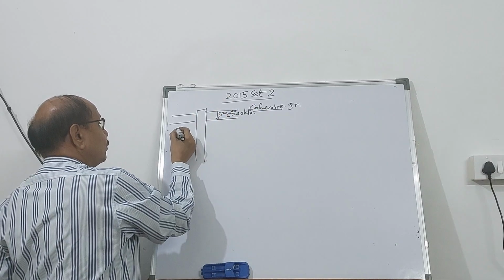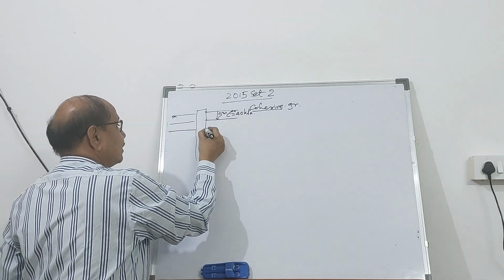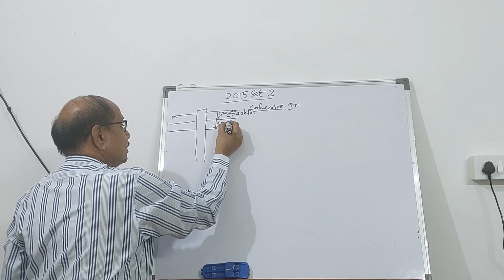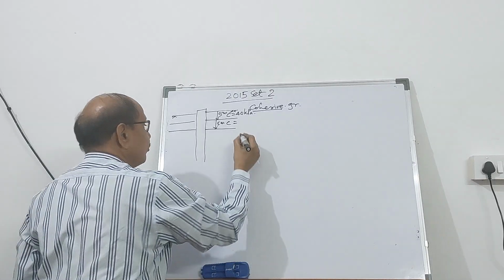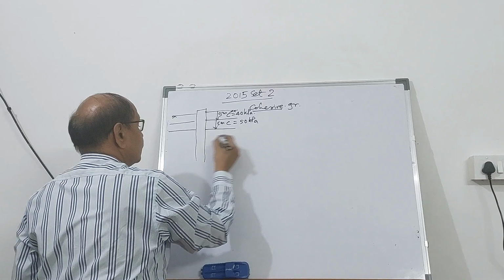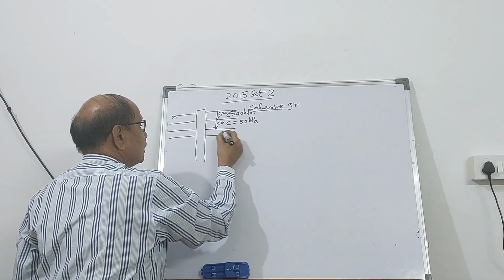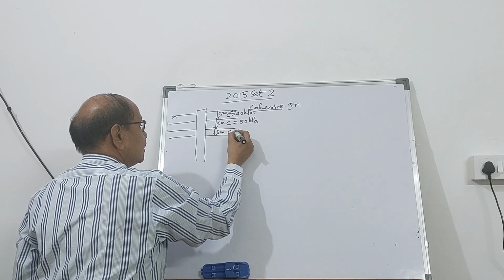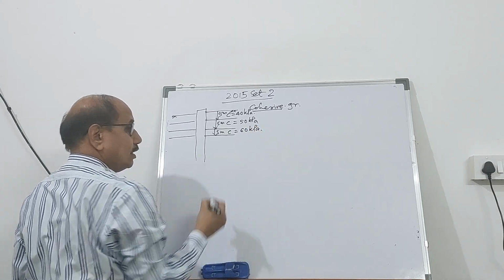And for the second layer, which is again of another 5 meter, the value of C is going to change. It is a layered one. It is 50 kilopascal. Then for the third layer of again 5 meter, C equal to 60 kilopascal.